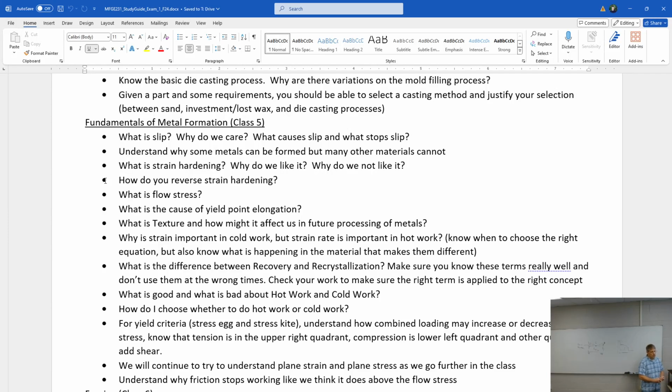Sorry, what is recovery? Recovery is when we go to this low temperature and we're rediffusing the interstitials out of the way of the dislocations. So we gain a little bit of ductility and don't lose much strength. Recrystallization is always hotter, like in our copper. Yes, because recrystallization is back to the hot work region so that the crystals start to grow.